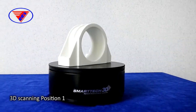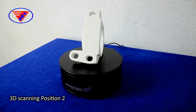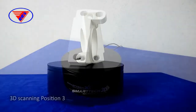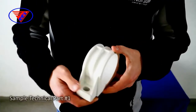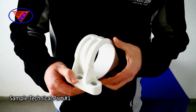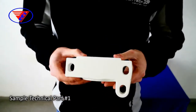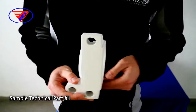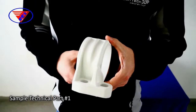Hello! In this video tutorial I will present the scanning and data post-processing of the technical sample part, which created triangle mesh can be used, for example, for reverse engineering. For the scanning process we used Micron 3D green scanner with the field of view of 400 by 300 by 240. To fasten the scanning process we will also use the rotary stage. Object will be scanned from 3 positions.